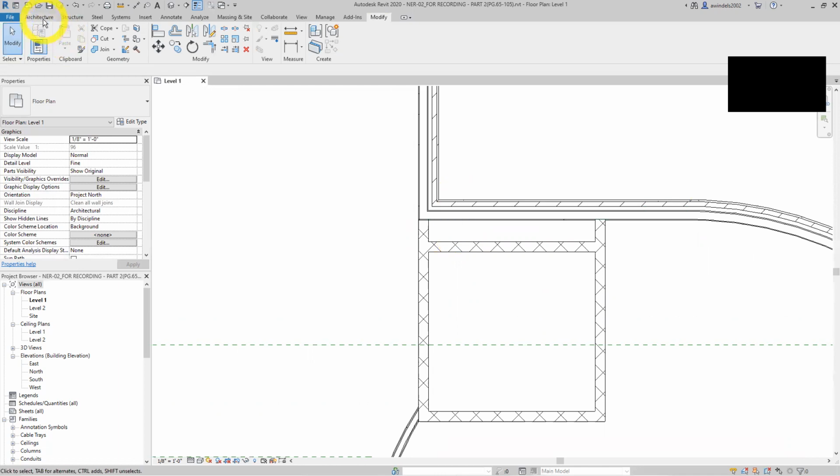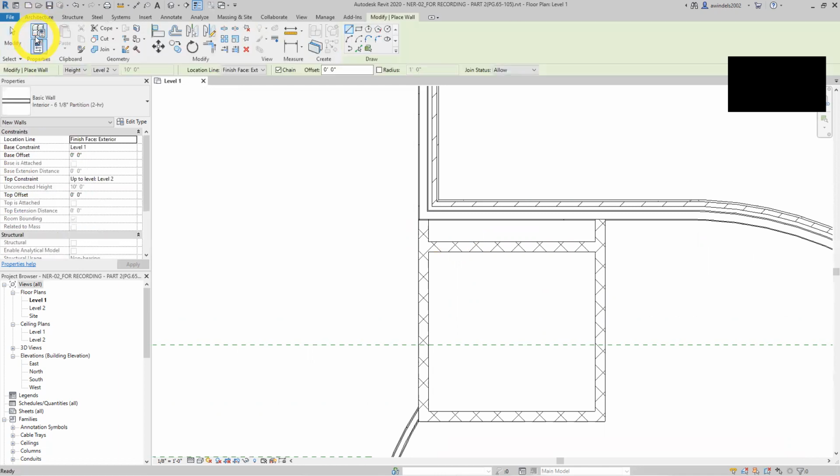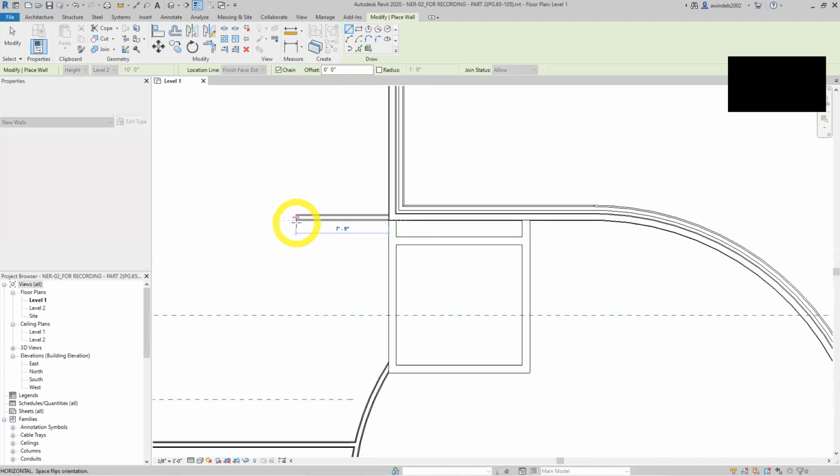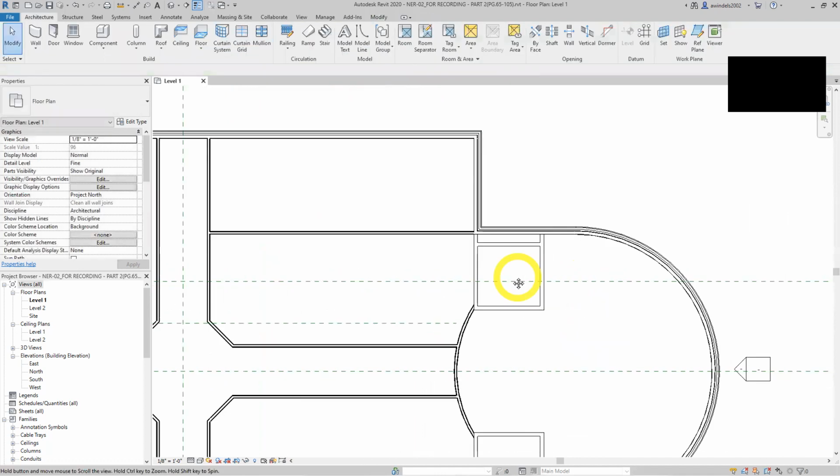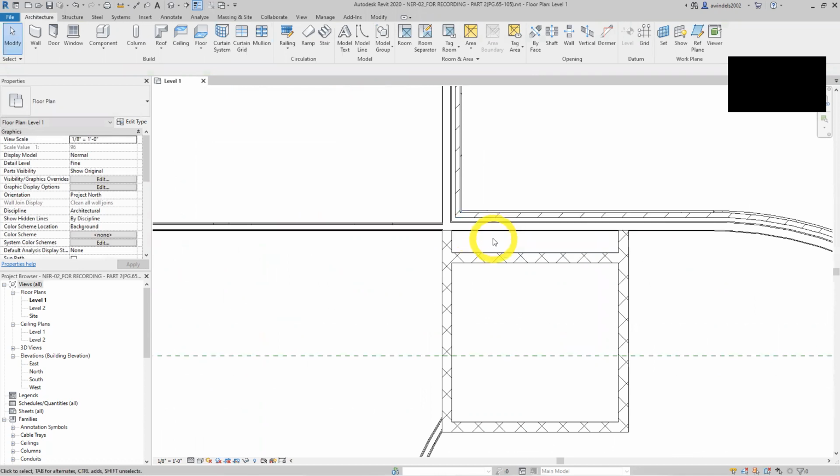Let's go to our Architect tab, Architect wall. Same wall still selected. Okay. Pick this one. Yep. Keep it there. No offset. Level 2 as well. And the elevation goes to, that's what we're picking. There. Let's go horizontal. Go to the middle of the wall. I always like to do that most times just to get it to join right. So we got that. Now, it's talking about wall joins and some options around them.